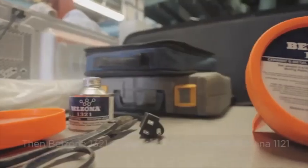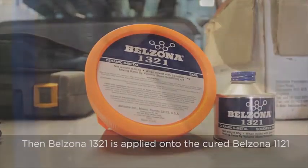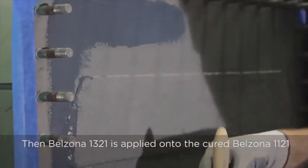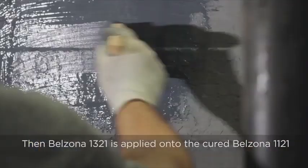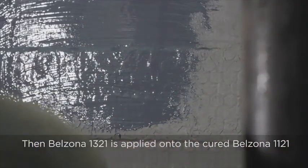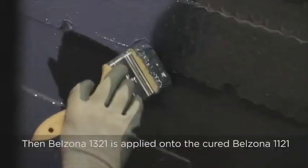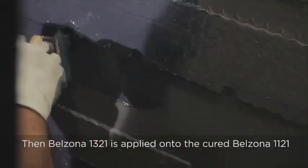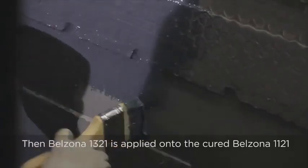going down the tubes, replace them if necessary, and then you can apply the Belzona 1321 or other ceramic-based coating directly on top of the Belzona paste grade, as long as you're still within that overcoating window. They used Belzona 1121 in this example because it had an extended working life and also an extended overcoating window, which meant they had plenty of time to apply this material on top.